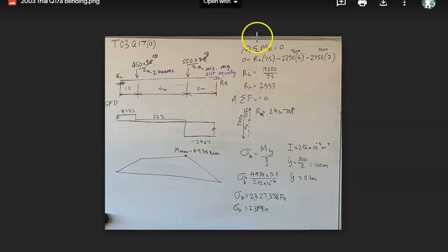So what we're going to do is calculate our reactions, which you can see I've calculated here, and I've got L and R. Once we've got L and R, we can then draw a shear force diagram, which I show looking like that. And we can reasonably assume that wherever we cross the x-axis is where our maximum bending moment is going to occur. Our maximums or minimums, right? Our turning points, if you do calculus.